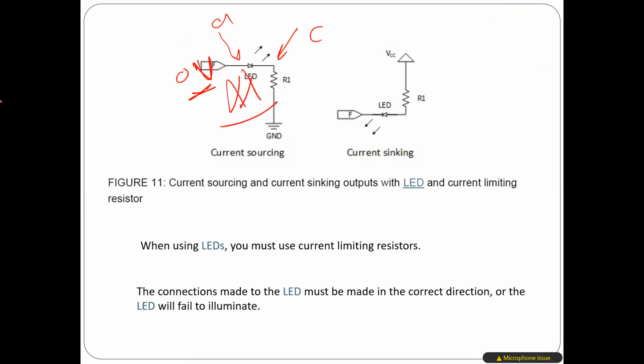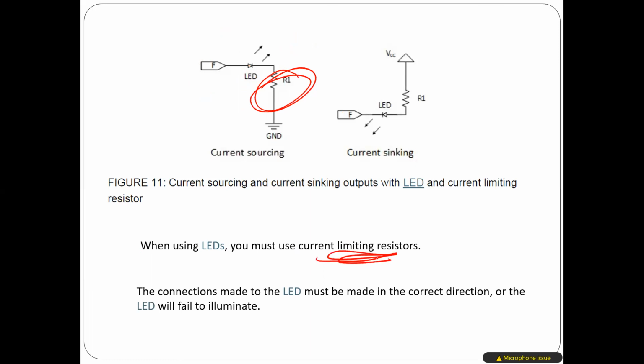Again, you need to ask the TA about two important things here. Very important things, please, guys. Number one, don't forget to connect the resistor. Very important, because otherwise you are going to burn it out. This resistor is to limit the current. Okay, this is number one.